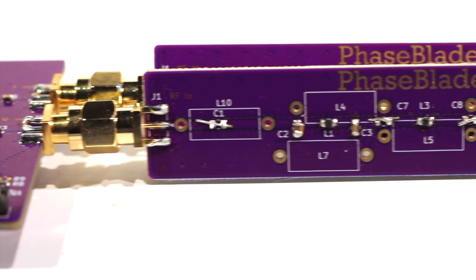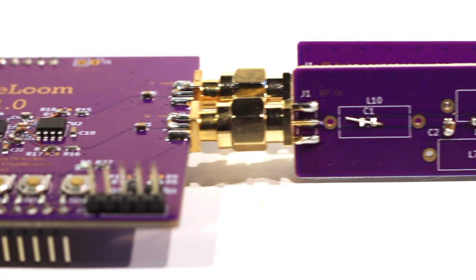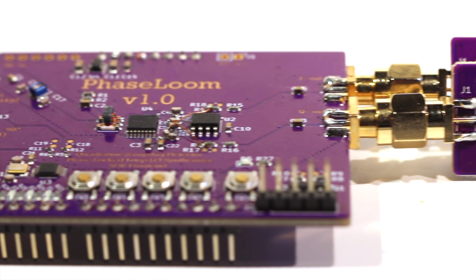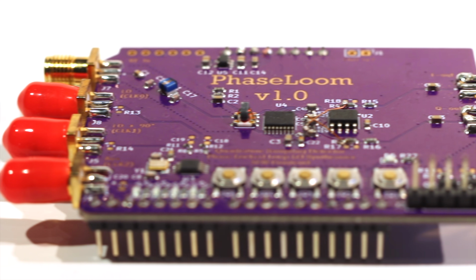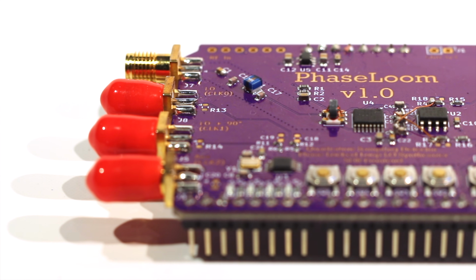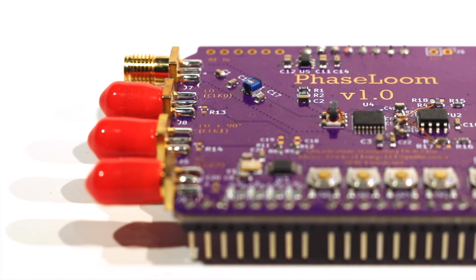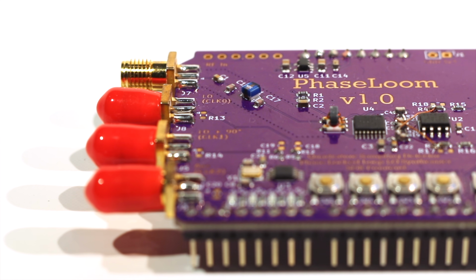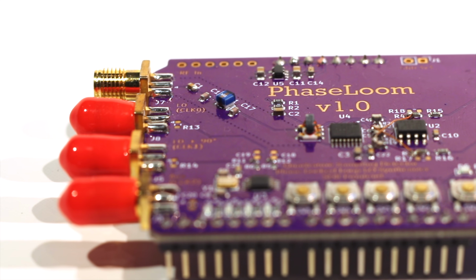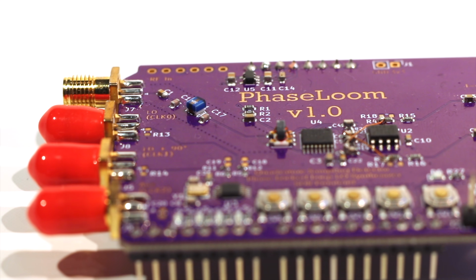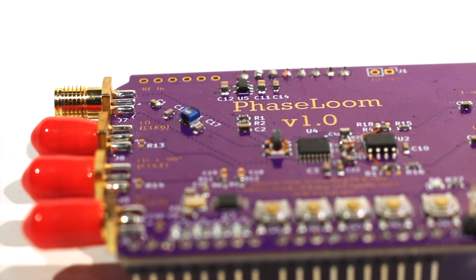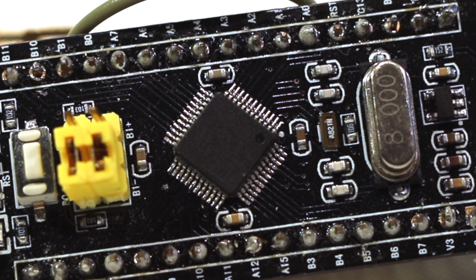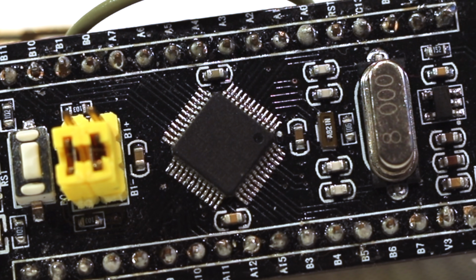You see, it's not too uncommon with some sort of ADC and a USB interface on some of the mid-tier MCUs, but more common than not, the ADC only has multiple channels muxed to a single ADC. And since we need both I and Q sampled simultaneously, we actually need two independent ADCs linked together, and this low-cost chip just happens to check all those boxes.